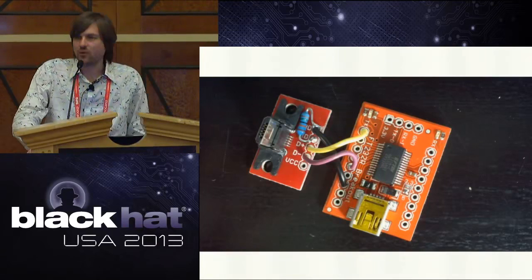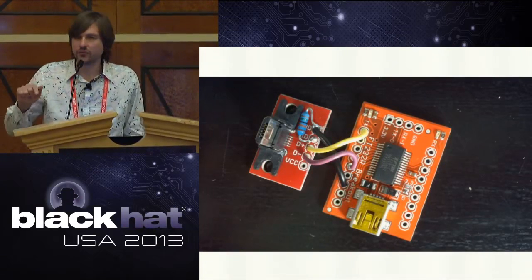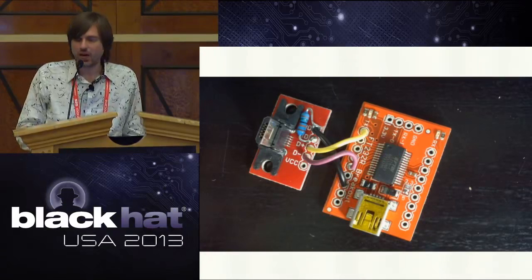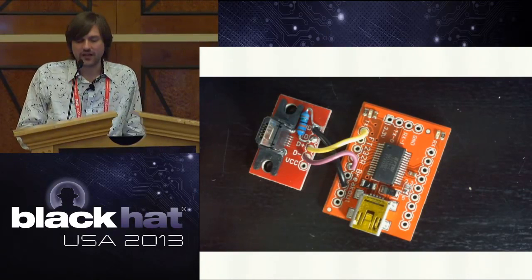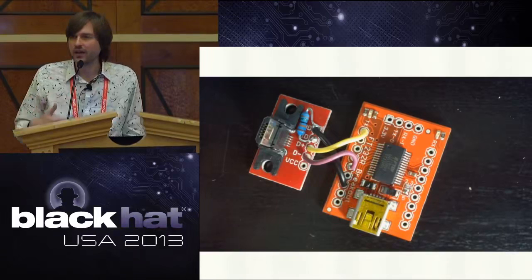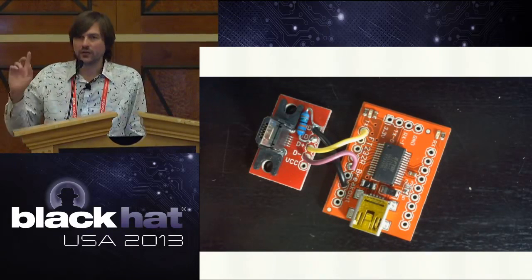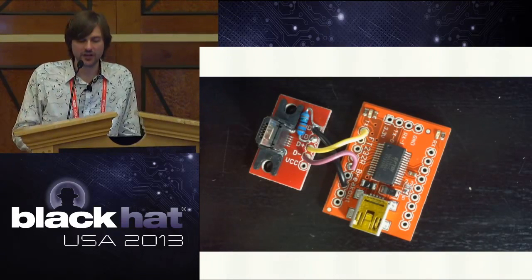Here we have a little breakout board on the left, which is a micro USB connector with, you can see, that blue resistor soldered in there. And then we literally just have three pieces of wire and a resistor is all we have to solder. And we connect this thing to what's on the right, an FTDI UART breakout board. And the FTDI UARTs are super common. Everybody uses them in the embedded electronics world. It's a readily available chip, and it's easy to find breakout boards like this. These are from SparkFun, but you can find similar things from a lot of other vendors.